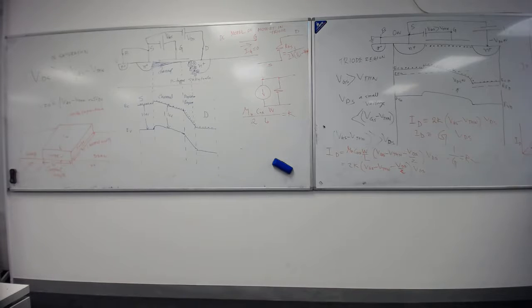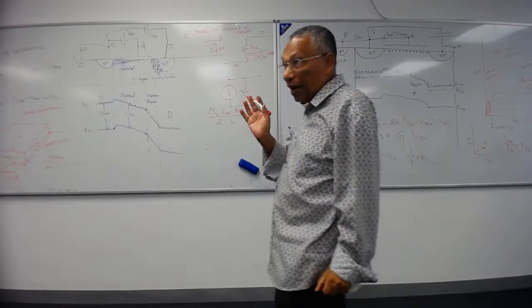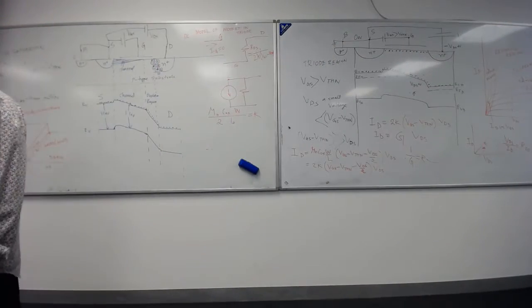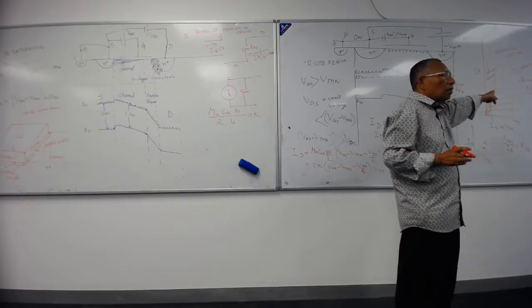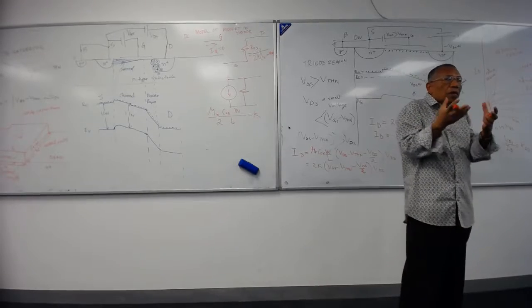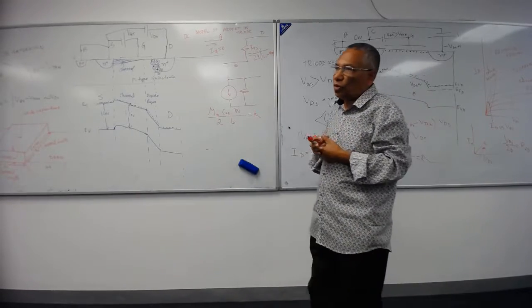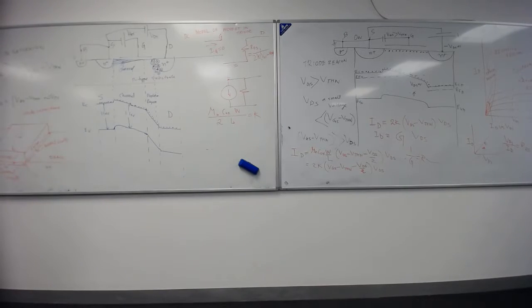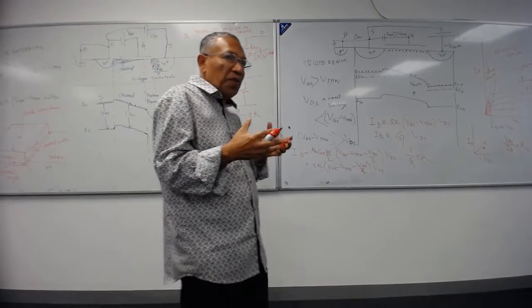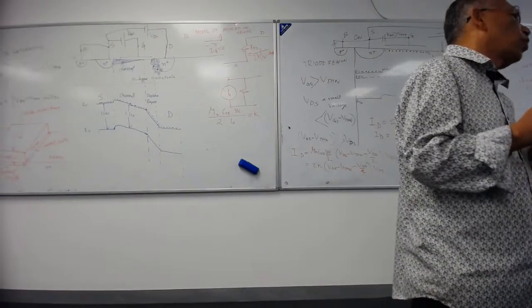It is driven by voltage. So in this case, for a given resistance in the drain, you have to know what gate voltage will keep it in the triode region. So no beta. You have to actually do it by knowledge of the device. So if you're using a certain MOSFET to operate as a switch, then you have to know something about the MOSFET: what current is produced in the triode region for what gate-to-source voltage.